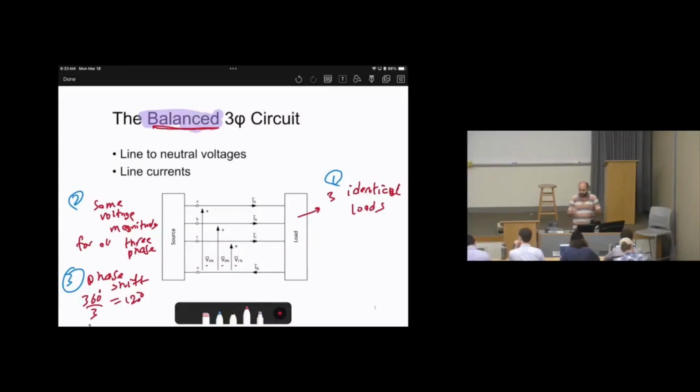In other words, you are connecting at phase A with 120 volts, angle 0. Your neighbor will be with 120 volts, angle negative 120. The other neighbor, 120 volts, angle positive 120. So when you have different angles, this will not impact the load. The load will run with any angle, there is no problem. But here, we choose this angle as 0, 120, negative 120 on purpose.